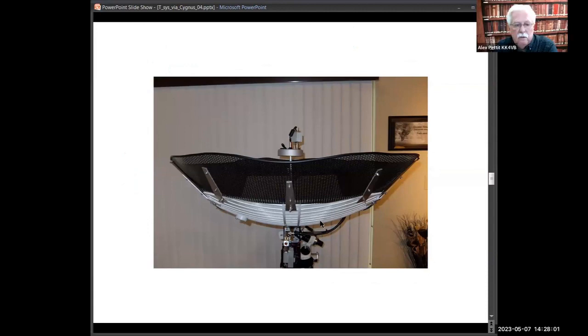And I also added aluminum screening in here because those slots did allow some ground noise to come through. Yeah. So the bottom end dropped about another dB by me adding screening over this. And the other contributing factor is the LNA. You have a very good LNA. It's a fairly low noise one. So the ingredients are there. Your hot cold measurement indicates a low system temperature. So that looks quite plausible to me.